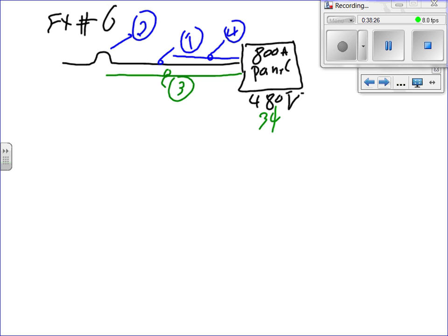We took the continuous load plus the non-continuous load plus the motor plus the HVAC, everything all together, came up with, say, 750, and I went up to an 800 amp panel, and I need to go and size things for it. Okay, 800 amp panel. For an 800 amp panel, I need to size the following.